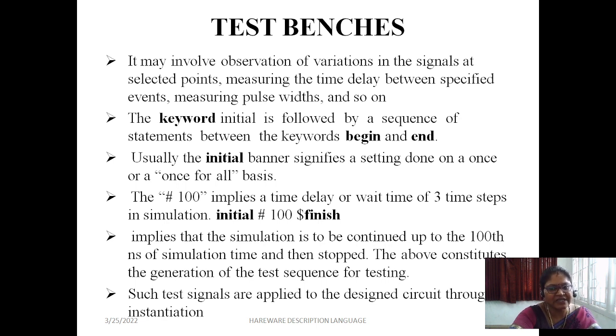Initially, the keyword initial is followed by a sequence of statements between the keywords begin and end. Usually we use the initial keyword in test benches, and then we use the begin as well as the end keyword. If you start with an initial block, it will be executed only once.